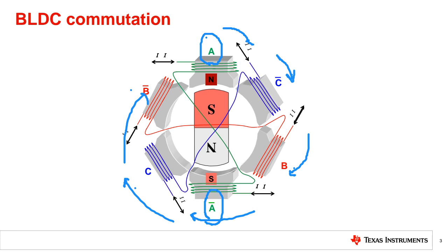The big distinguishing factor between brush and brushless DC motors is commutation. Don't forget it. One of them is mechanically commutated, one of them is electronically commutated. In a brush DC motor, the commutation is automatically handled by the motor's mechanical design, and you can learn more about brush DC motors.